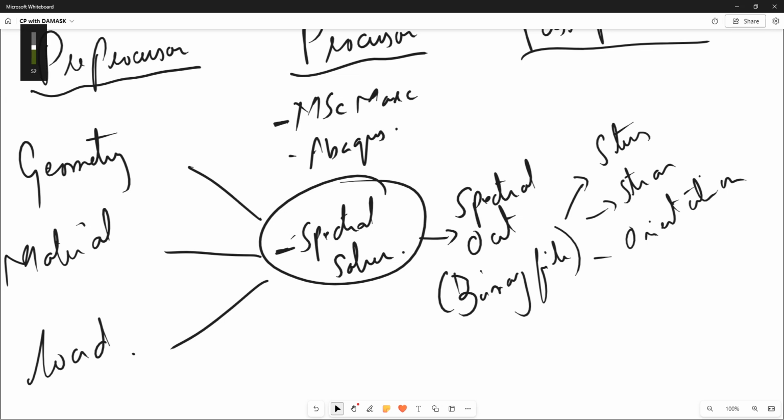So which slip systems activated, what was the energy of each slip system that activated, which crystals deformed more, which crystals deformed less. So when I say stress, strain, or orientation, basically every parameter that resulted in this as well. These are very high level parameters, but we can obtain any information below them as well, whichever is calculated in this binary file. But generally we are more interested in looking at stress, strain, orientation change, and so on, and then we can plot it in different or multiple ways, and that is what you will see in how people present crystal plasticity data or information in more meaningful ways.